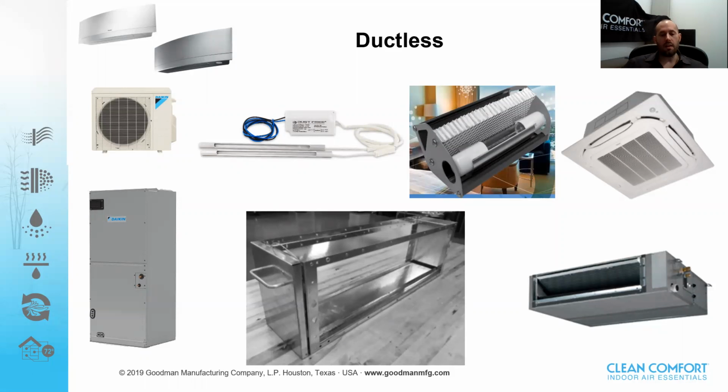Ductless. Now, with ductless, if you're using an air handling unit, what I would call a ducted ductless, you have a ton of options. But if you have a high wall unit, you're basically stuck using the pencil-sized UV light. It's the only thing that's going to fit in there. Cassette units, you can use the small UV, you can use the small air purifier, and usually they can bring in a small amount of outside air. Concealed units are basically the same as the cassettes, but you could possibly add an air filter to those units, but you really got to look at your static.